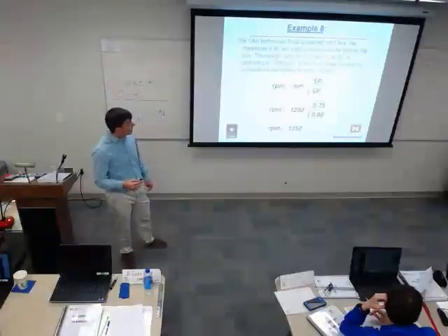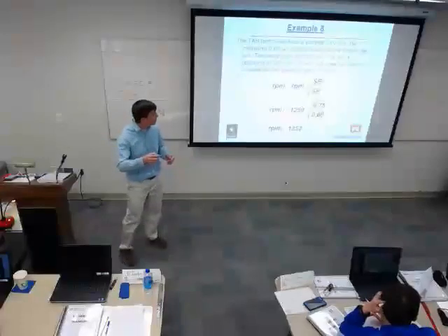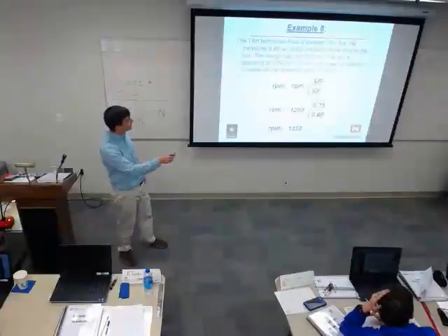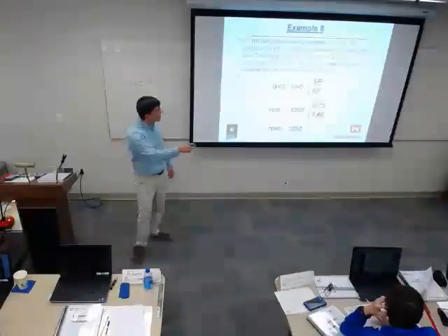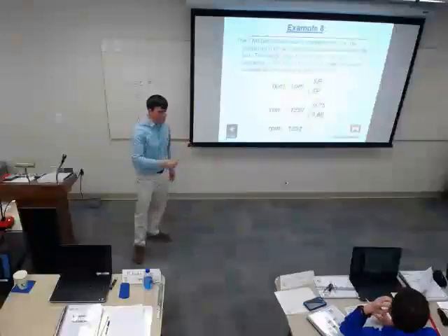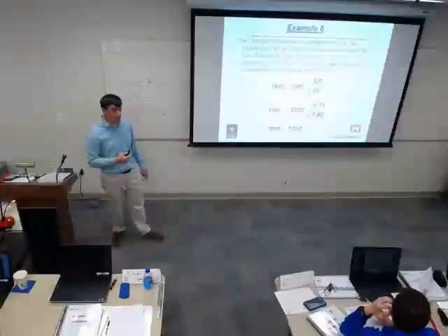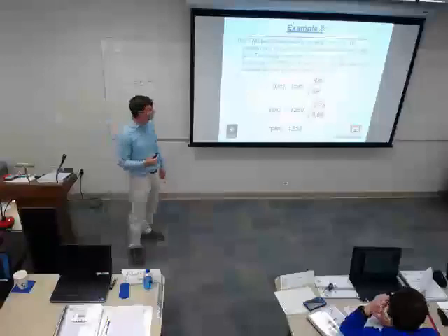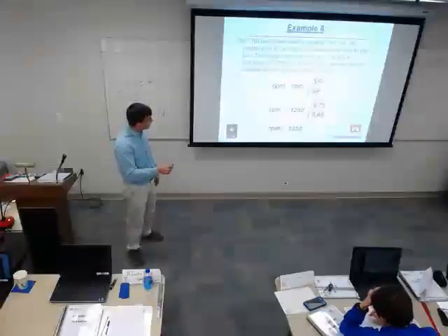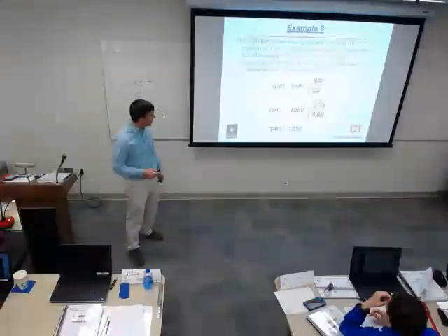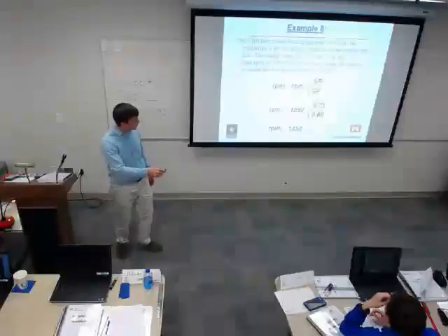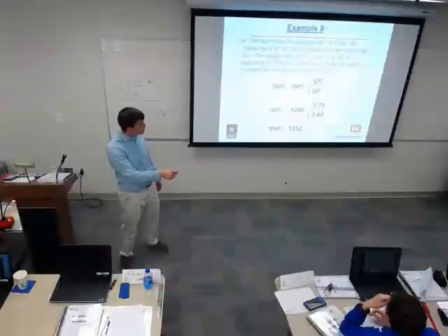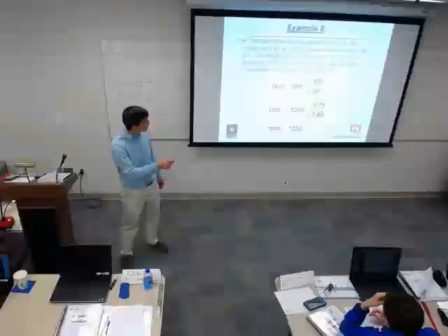So I go out in the system and I measure static pressure. It's 0.6 inches. And most VAV boxes, this is kind of realistic, need at least 3/4 of an inch on the incoming side to operate correctly. And I was back at that same number of 1250 RPM. So in this instance, I knew static pressure 1, that was 0.6.